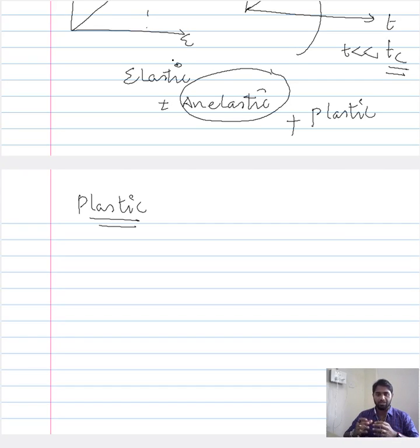So, the amount of stress that is required to facilitate the free propagation, or the ability to overcome any obstacles present in the slip plane because of the pre-existing dislocations, needs to be higher. You need an additional amount of stress, an additional amount of energy, for the dislocation to propagate easily in the slip plane.